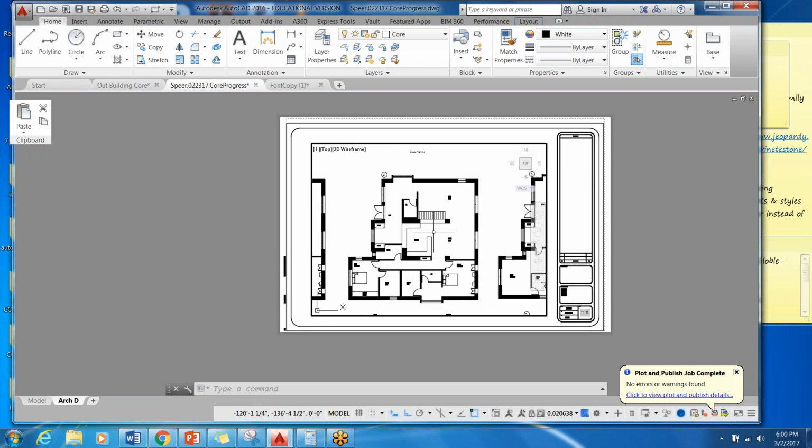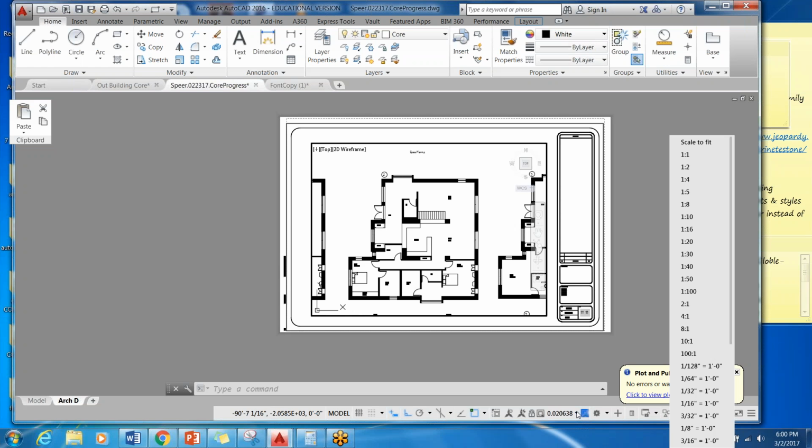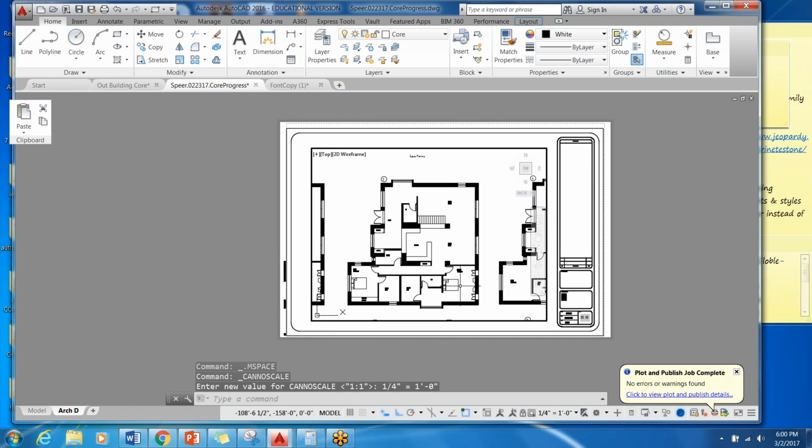So Shemaine really likes number 2, but I want it to be to a right scale. Right now in the lower right-hand corner, it's some odd decimal that's not very helpful to the architect. And I could click the drop down arrow to find common scales that would be on my architectural ruler. Okay, so if I scroll down a little bit more with this lighter medium gray scroll bar, I can see a quarter, 3/8, 1/8. We're going to do a quarter. So I was pretty close.